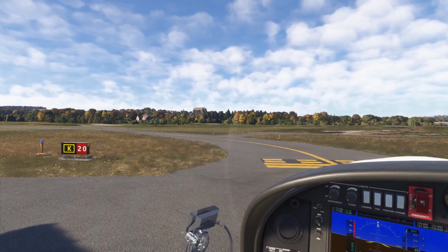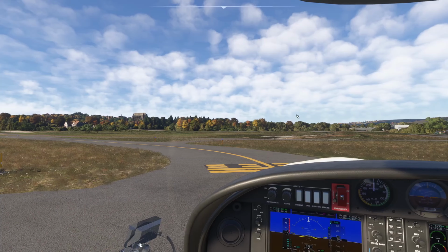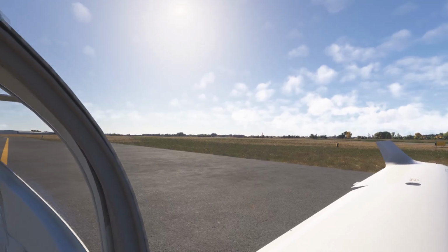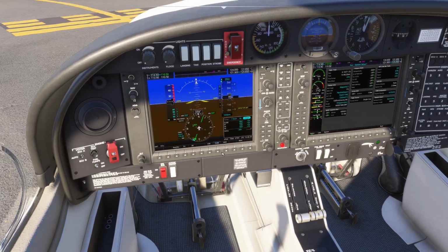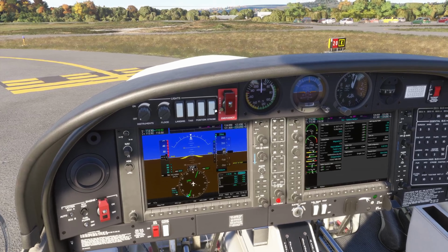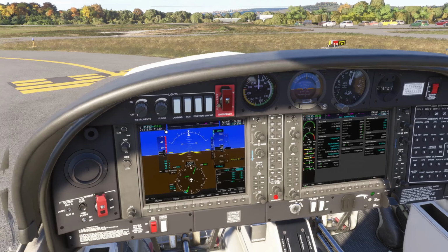And we want to perform our ATPL flow. So, approach path is clear, runway clear. Transponder, code is set, out. P, pitot heat. Below 10 degrees we would turn on, but it's above, so we'd keep that off. And lights. Landing light, strobes on, taxi light off.